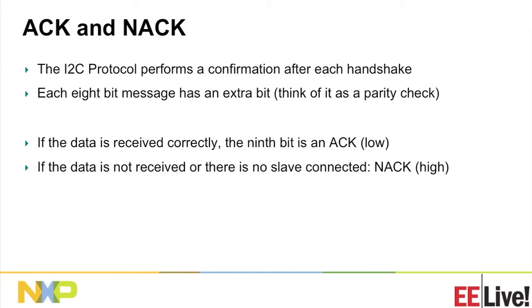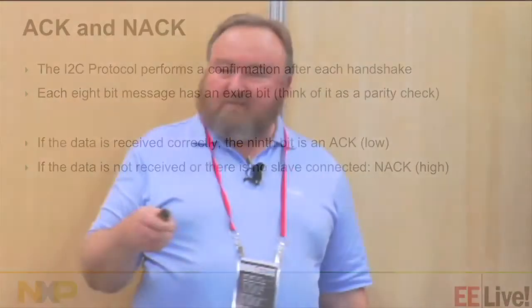And this, as I said, is probably the most single important feature of the I2C bus. It is also probably the biggest headache because it means that traffic on your bus is traveling 8 bits from master to slave, then 1 bit in the opposite direction, slave back to master. Which means that the information on the bus is constantly traveling back and forwards, and anything you put on the bus has to tolerate the fact that the direction is changed automatically.